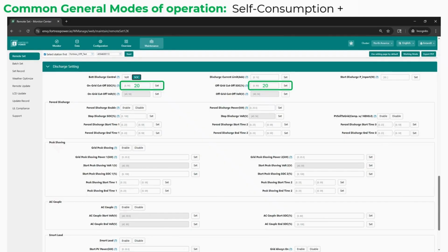But after the PV production has returned to zero or has reduced that it cannot accommodate for all the loads, the battery will be supplementing the PV so that the import from the grid is reduced, thus in attempt to reduce the electricity bill by the end of the month for the site where the system is installed. That's the whole idea behind self-consumption.